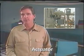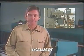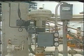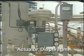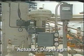There are also instruments that move or actuate valve stems. These are called actuators. Actuators receive signals from a controller. Here's a valve with an actuator. The pancake-shaped device on top of the supporting yoke contains a diaphragm. The diaphragm is operated by compressed air, and it moves the valve stem up or down.